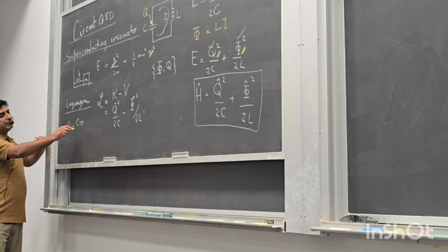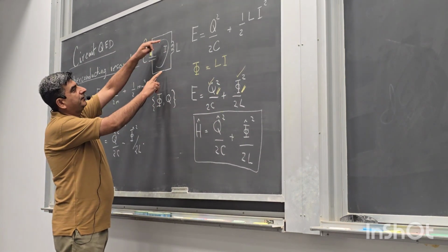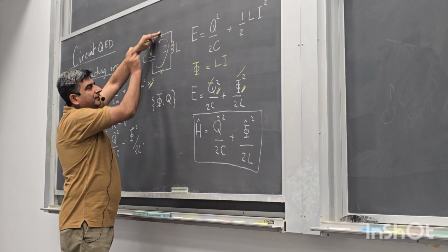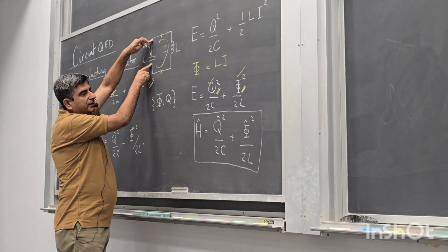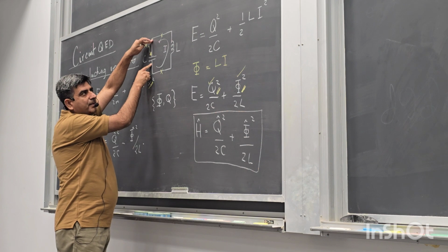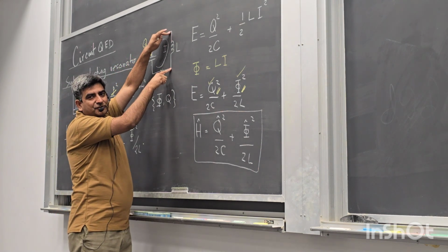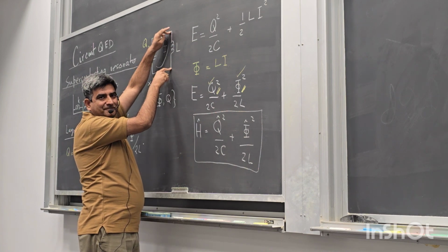Correct. And I know that this voltage is developed across these two terminals. And Kirchhoff's voltage law means that this voltage is going to appear across the capacitance. But the voltage is, from Faraday's law, just the rate of change of flux of the system.